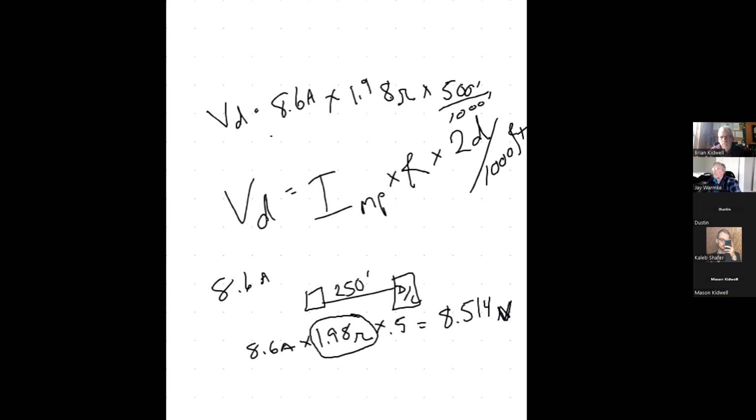Or I could increase the voltage of my system. Well, what if I increase this to 600 volts, coming from my array and then stepping down? Well, at that point, 8.5 volts out of 600 is only 1.5%. Well, now we're within the realm of acceptability. So this is one reason why we want to increase the voltage of our system as much as possible, because we want to,